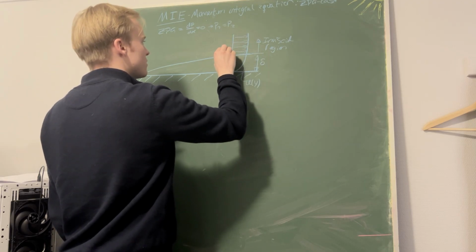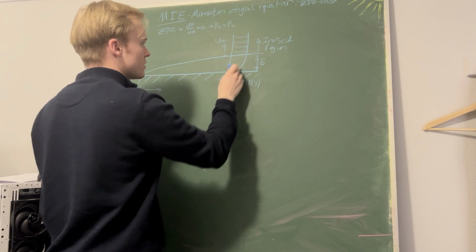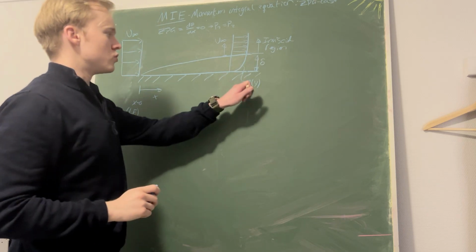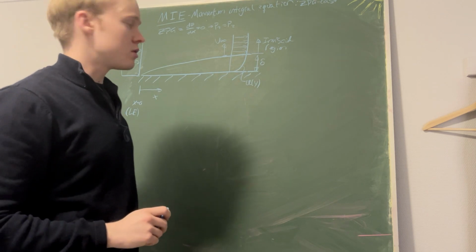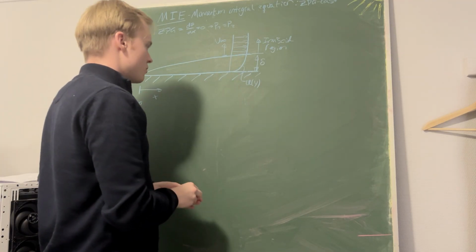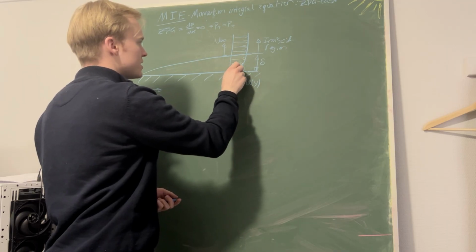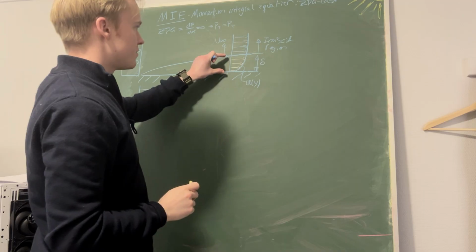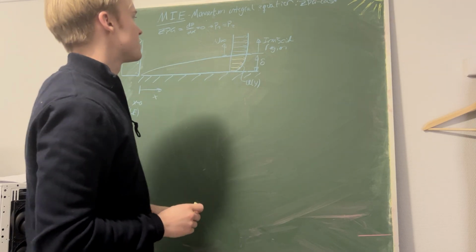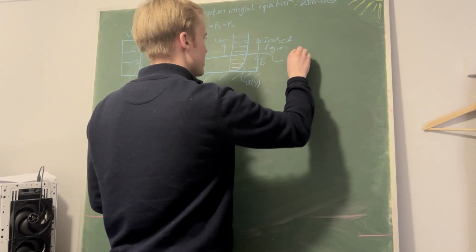So from here on and out we have U infinity, and from the boundary layer down to the wall we have U of y with the no slip at the bottom. So I can draw it like this as well. So this is our viscous region below the boundary layer. You can also say that this is the boundary layer.